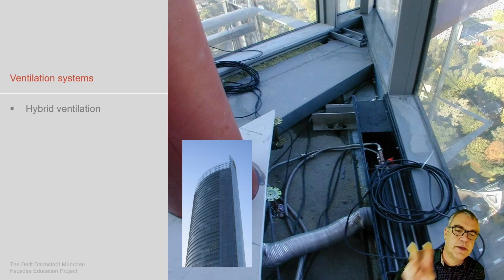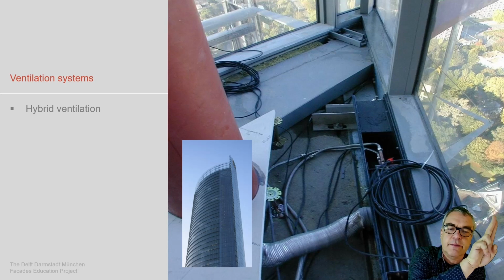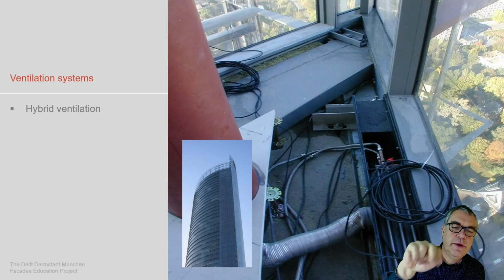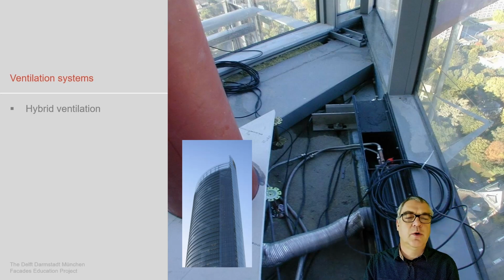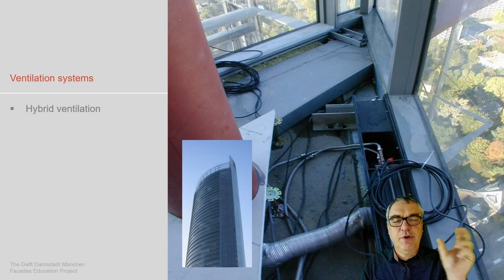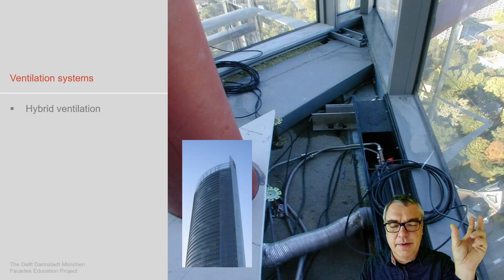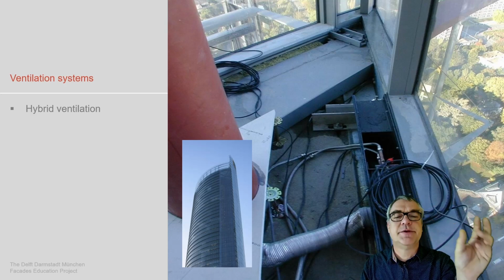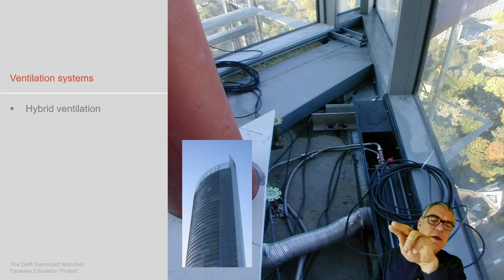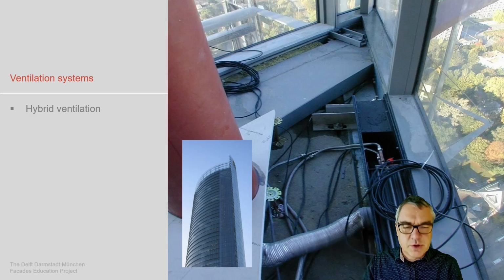Looking at this one, it's a double facade at this area of the slide. Then there's the heating and cooling device, which exhausts the air into the system. And as we know, in this entire building we have some preheated air in the cavity of the double facade. Then this is conditioned, and that's the mechanical part in here, and then exhausted through the building and out of the solar chimneys, which are brought into position here.